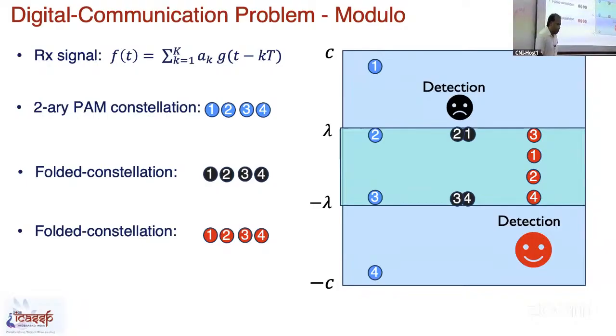Now let's look at a simple scenario where we are having only quantization noise. So we have a huge dynamic range ADC first, and now we have a small dynamic range ADC. What can we say about the quantization noise? Will it be same, higher or lower in our case after folding? After folding, of course, we are using lower dynamic range.